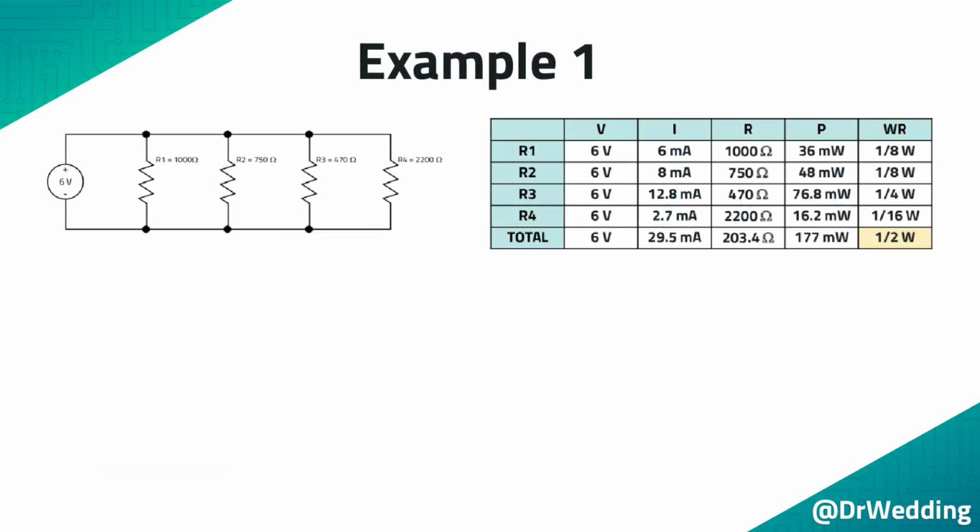Let's apply this law to a parallel circuit that we have solved in a previous video, because we already know all of the currents and voltages for this circuit. Example 1. Verify Kirchhoff's current law at the highlighted node. Start with the equation for Kirchhoff's current law. We know the 2 red currents. They are the currents through R3 and R4. We can use these 2 red currents to find the blue current.